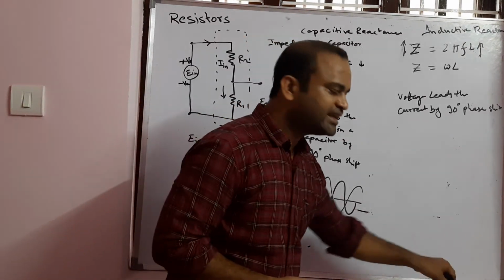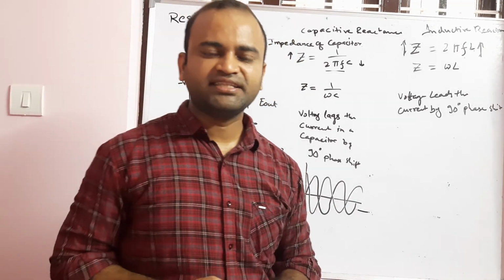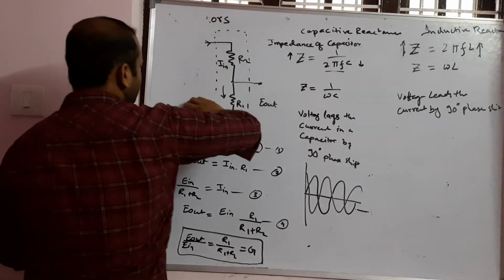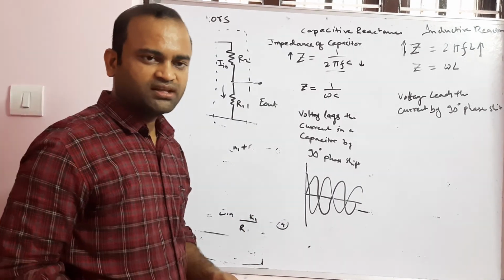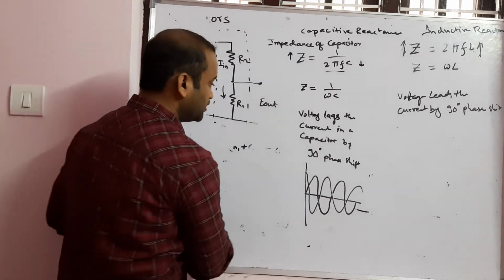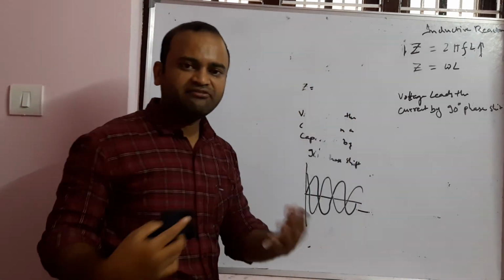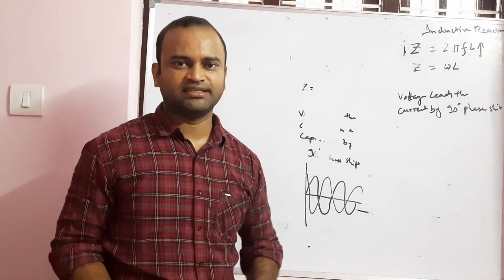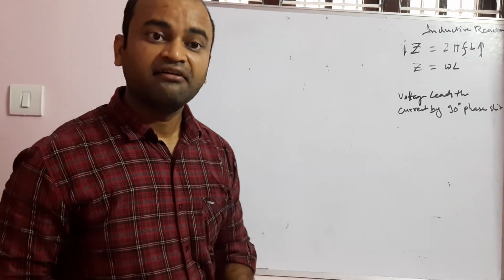Now, with these electrical properties, we can further discuss that using these electrical elements, we can separate the various frequency components in a signal using a circuit. For example, we can design a circuit which allows the low frequency signals and attenuates the high frequency signals. Then that particular circuit is known as a low pass filter. That means it is filtering out the high frequency components of a signal and allowing the low frequency components of a signal.